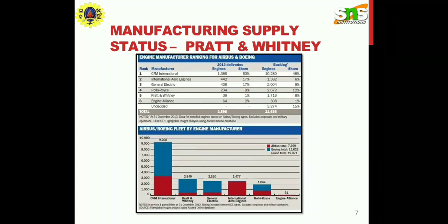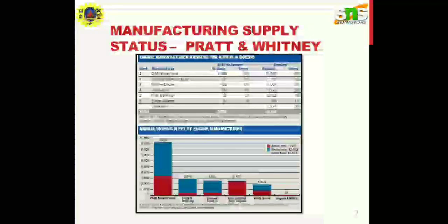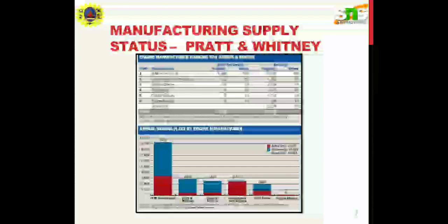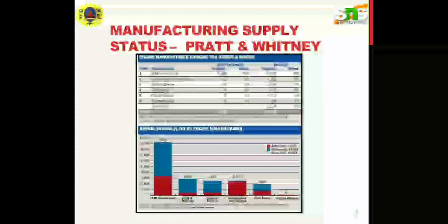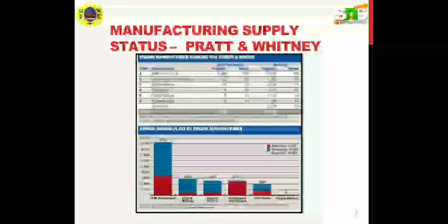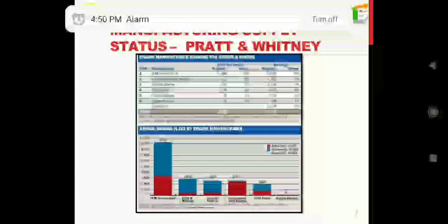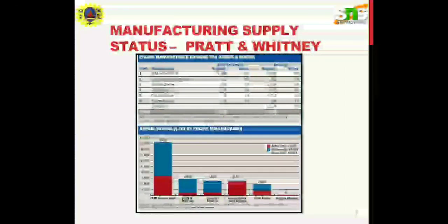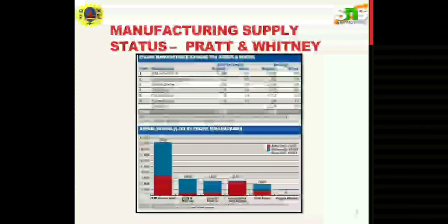Velocity will decrease over the rotor. Here a Pelton wheel is an impulse design. Reaction turbo machines operate by reacting the flow of a fluid through airfoil shaped rotor and stator blades. The velocity of the fluid through the set of blades increases slightly as it passes from rotor to stator and vice versa, and the velocity decreases through the set of the